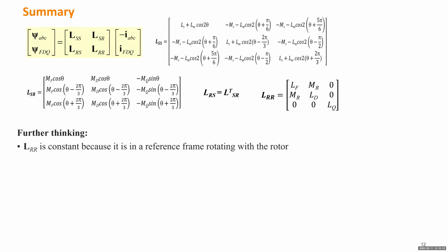So it's not a good model. A good model means first, all the parameters have to be constant. Because when you test this machine at this location under this condition, you can pass the parameters to somebody else, and it's safe for them to use the same set of numbers for other studies. You don't want everything to change when you disconnect the generator, shifting to some other value. All the modeling work would be useless.